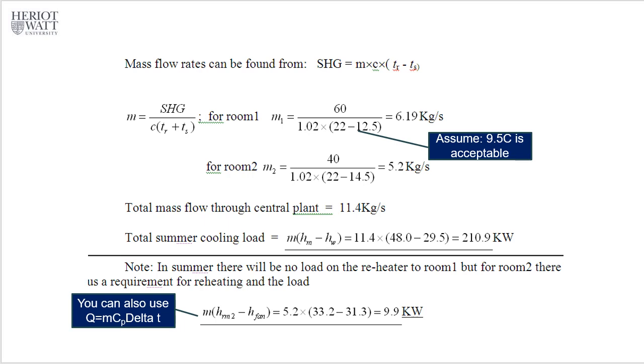Remember, here we have to be careful because there's a 1.5 degree free gain, that is gain from the ductwork. So therefore the heating is not done by the heater, but actually obtained as heat during the journey from the air handling unit to zone 2. So therefore you take this out.